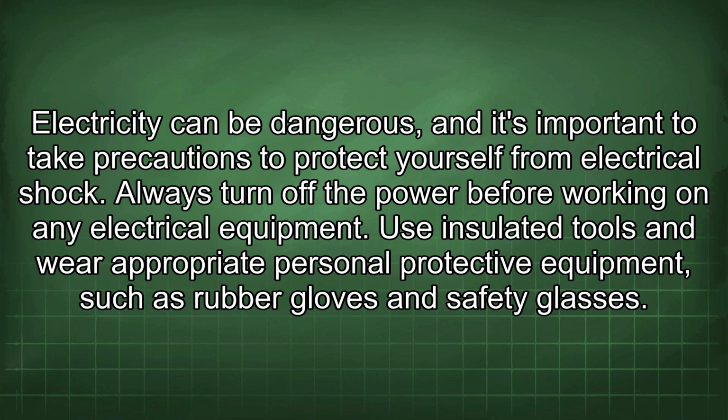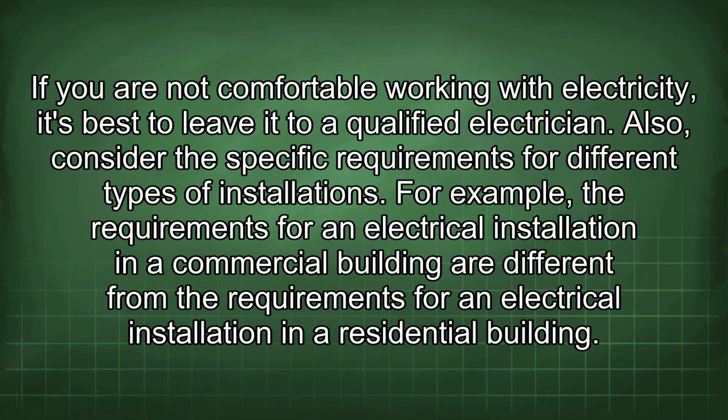Always turn off the power before working on any electrical equipment. Use insulated tools and wear appropriate personal protective equipment such as rubber gloves and safety glasses. If you are not comfortable working with electricity, it's best to leave it to a qualified electrician. Also, consider the specific requirements for different types of installations.